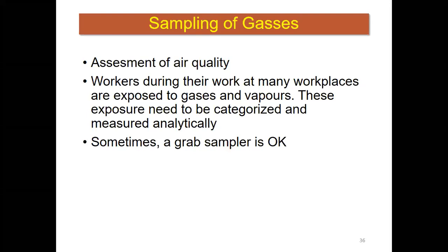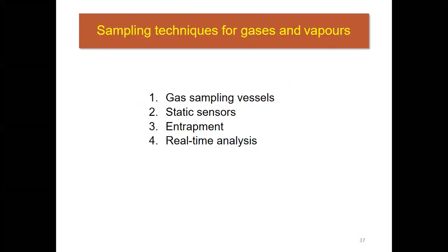When we talk about gas sampling, sometimes a grab sample is okay. So what is a grab sample? A grab sample is a sample which has all the test materials and can be collected at one time. We discussed this last week. Normally liquid samples can be considered grab samples, but solid samples are not, because a solid is a heterogeneous mixture. When we talk about gases, in most cases gases form a homogeneous mixture. Therefore, a grab sample is okay, right?